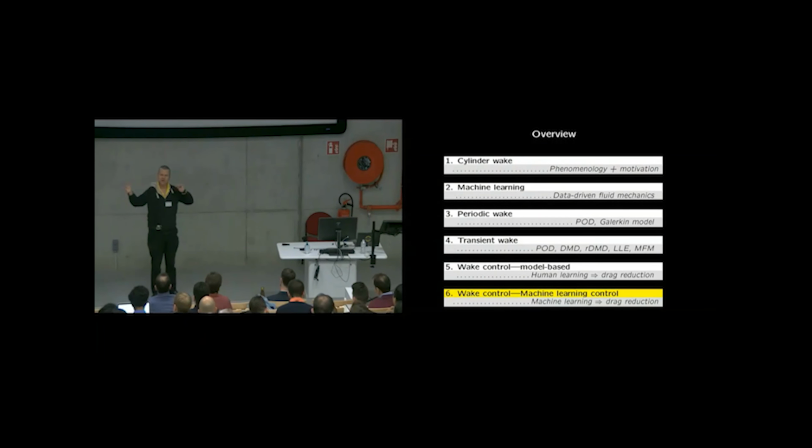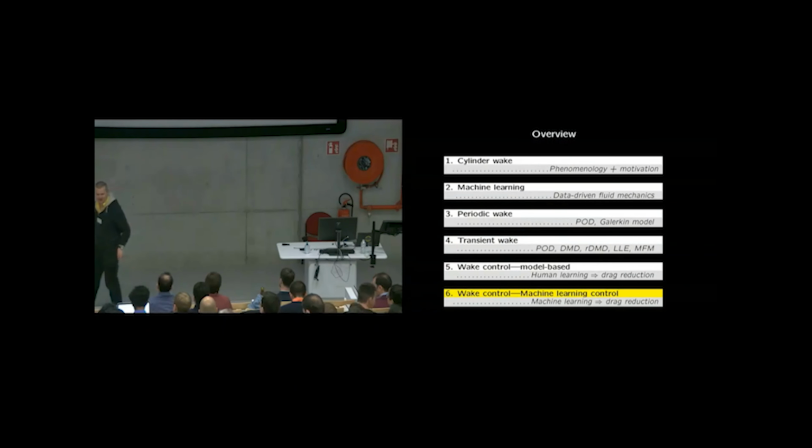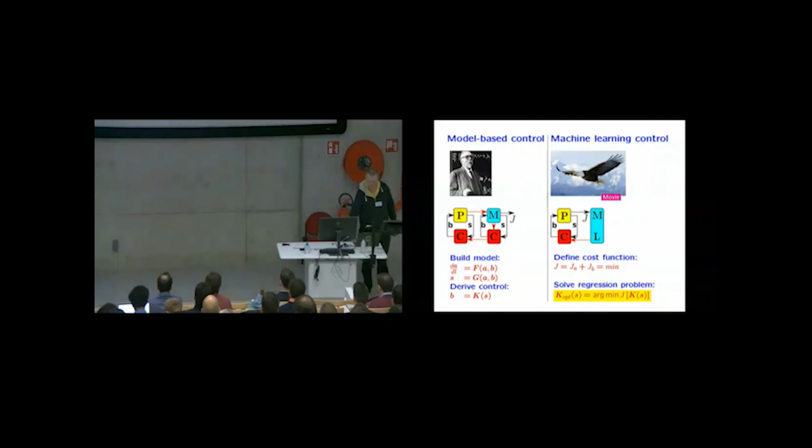You can stop your actuation. So doing the transient from the forced flow to the stabilized flow, you can stop some modes. But maybe you have to add some other modes. So even for this simple case, you are in trouble. As you are going from an actuated state to a natural state, it's very difficult to describe it with one set of modes and doing a control-oriented model. And with that, I want to conclude with a solution of this problem, which we have called machine learning control.